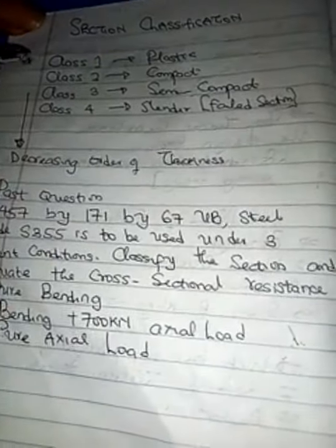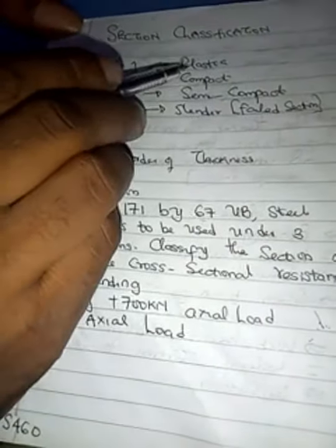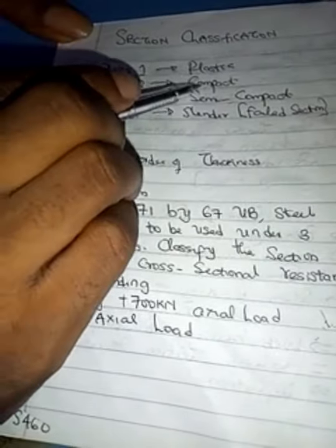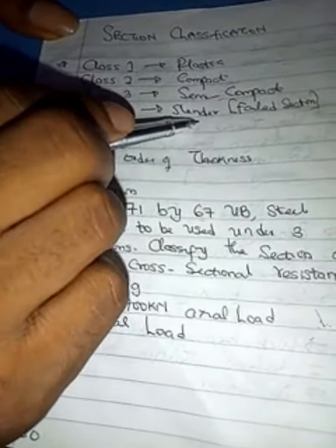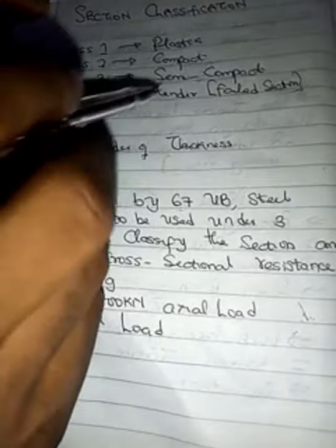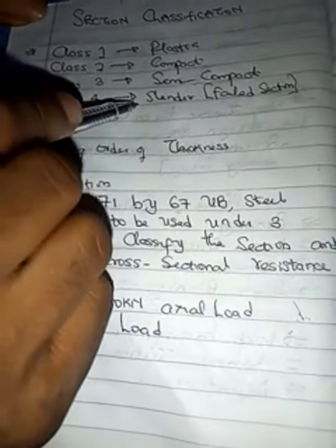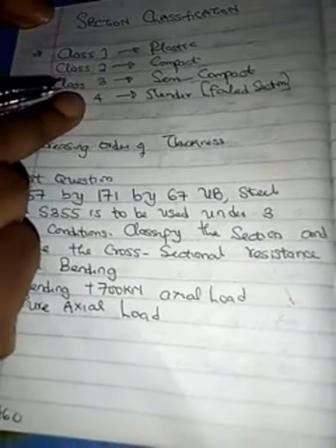What this topic is mainly about is you taking a steel section and telling us if the section is plastic, compact, semi-compact, or slender. The man mentioned to us that we have no business testing for slender. Once we have any value that tells us it's a slender steel section, then it is a failed section. So we will not be dealing with slender at all. We are going to focus on class 1, class 2, and class 3 steel.